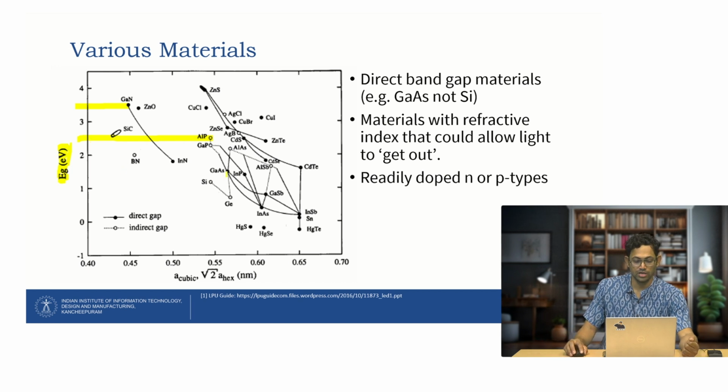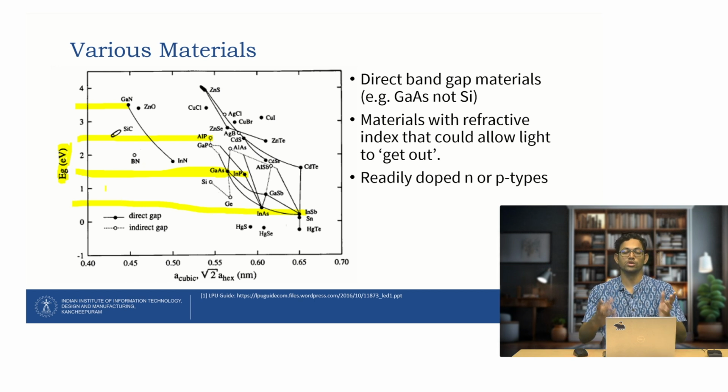Okay. Then you have gallium arsenide. Gallium arsenide has an energy of around 1.5. So with gallium arsenide or indium phosphide, you would be able to emit light in the red region. If you go even lower, indium selenide and indium arsenide, it's around 0.5 eV, which means you can go into the NIR range, using NIR band 1 or band 2 energy light sources. You can use those as well. Okay, so based on the material, we can choose which light we want to emit. That is very important to know.